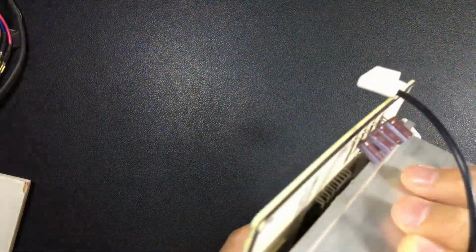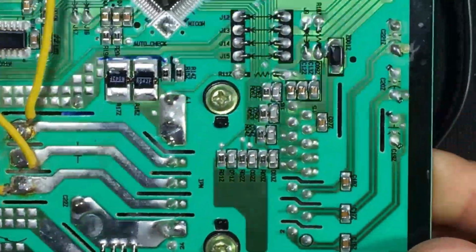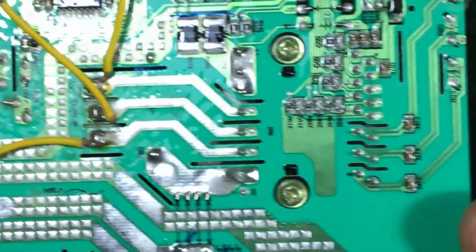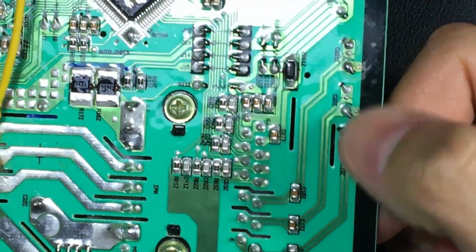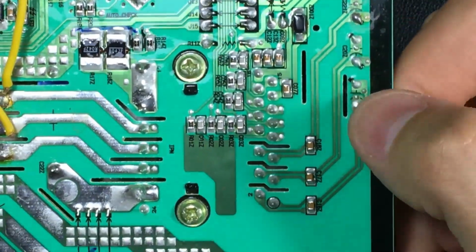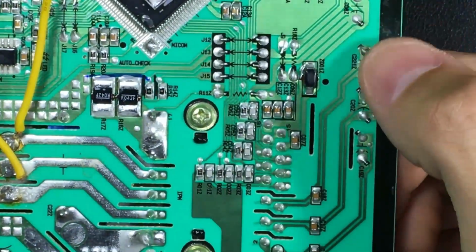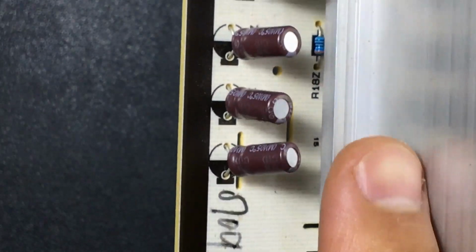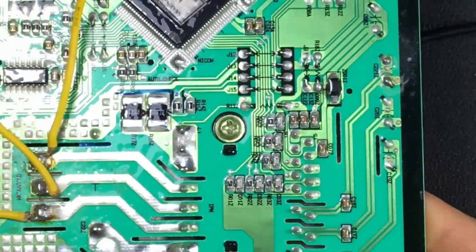We will see the board of an LG inverter and see that the power capacitors of this LG are very visible. In fact, if we look at the board from above, at this point we will already have the test points of those 15 volt capacitors. Clearly there are capacitors here that go directly to power the IPM that is in this area. In this case, we can measure the 15 volts without completely disassembling the equipment, not even taking out the board. And here are the capacitors that keep those 15 volts. Moreover, they are much simpler capacitors.